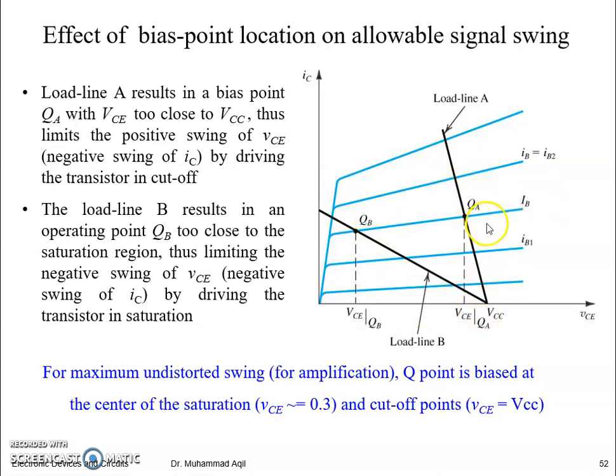See, if the designer had designed the RC and RE and the VCC to have this load line and set its Q point QA with all these parameters, then this is the DC VCE and IC he had set, right?